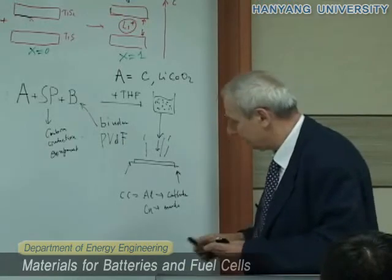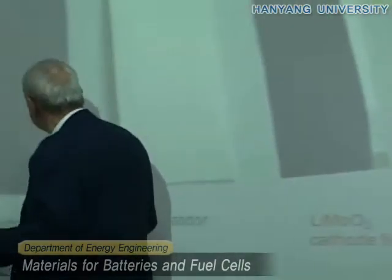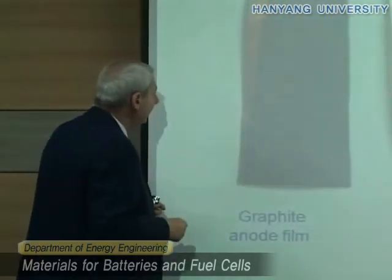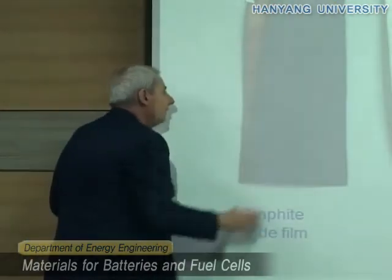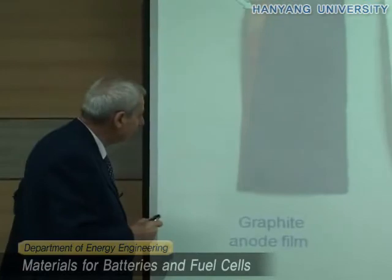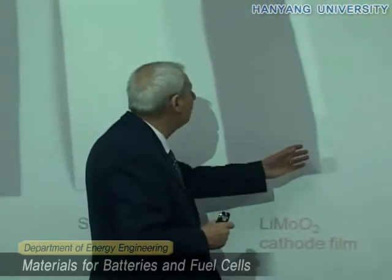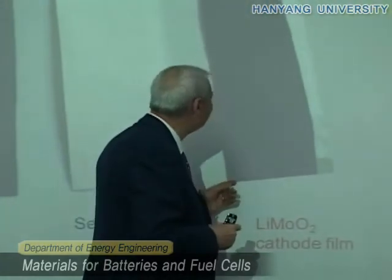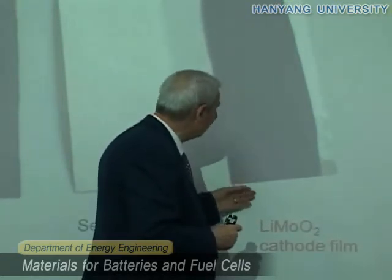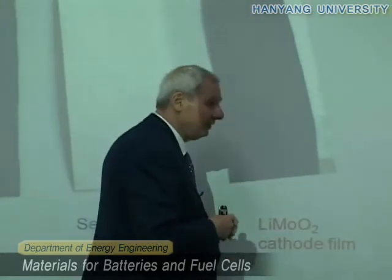So we will have a film formation, which you can see here. You can see in the back the copper current collector, and this then is a film of graphite with a binder and carbon. And this is the same thing: we have an aluminum current collector, and on it we have a slurry of lithium cobalt oxide, carbon and binder, so we have a film.